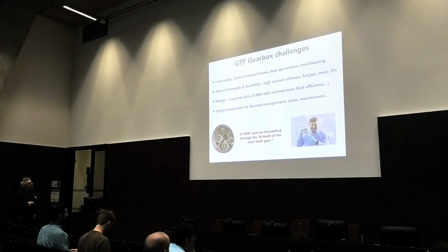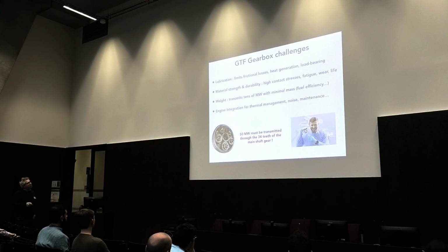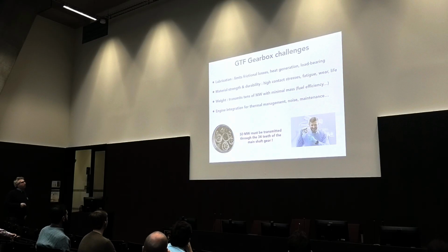If you want to talk about the number of teeth on the gear of the main shaft, you have about 34 teeth, and these 34 teeth have to transmit a power of 50 megawatts. So it's quite huge for one tooth. So you have to take care here, as depicted in the picture, of all of these teeth.